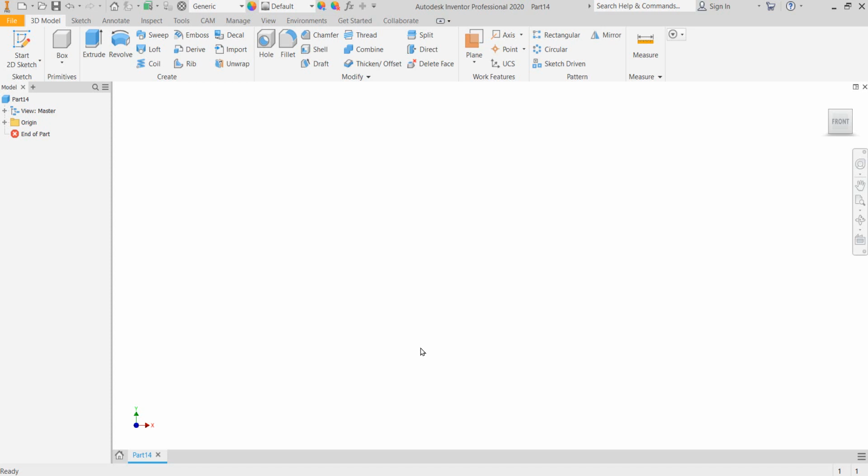Okay, so we're going to start out with one, and we're going to split it into two separate. It's called top-down design. It's different than what we've been doing. Most of what we do is bottom up, which we start with individual parts and then work towards the assembly. With this one, we'll start with not the assembly, but a parent part, if you will, create the common features and then split it and then work on the individual parts to create our assembly.